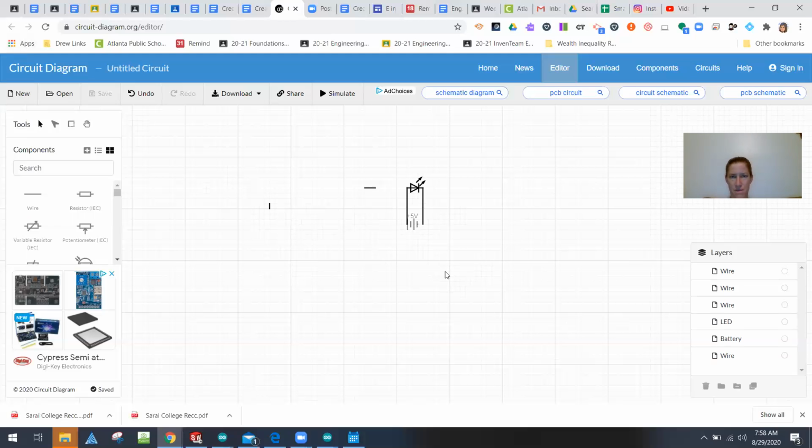Okay, so it looks like the way I'm drawing this here, do you see right here how the wire is not connected? I can see that there's a wire that's not connected. I've got to make sure that it is connected because we just described the fact that current only flows in a closed loop. So it's not a closed loop. So let's go ahead and do that. And then technically this would be a correct representation of our circuit.